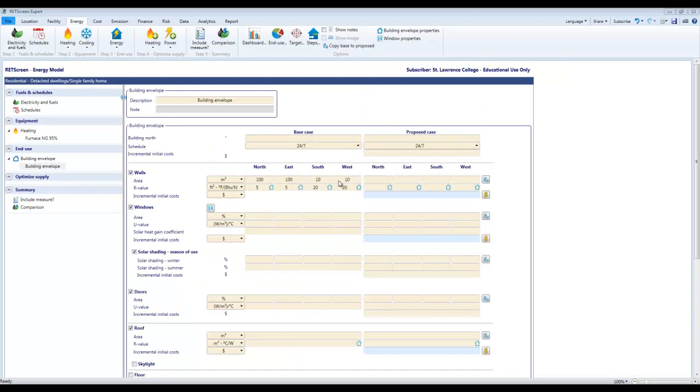So I've just entered some numbers in here for wall areas, and in this drop down here we've got a choice of 4 different sets of units for the thermal properties of those walls. This is metric, also known as RSI values. This is imperial R values. These are the common R values, like what you go and buy R12 insulation. That's the units for that.